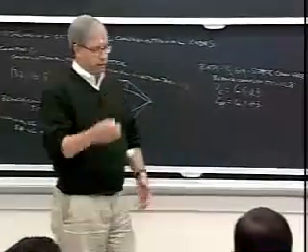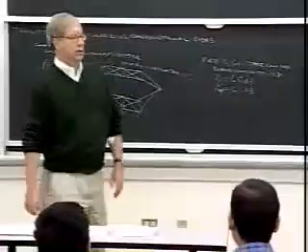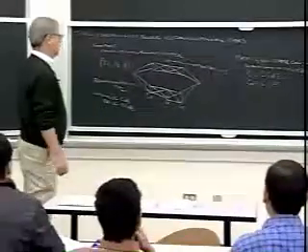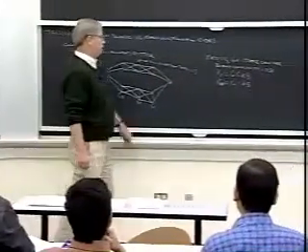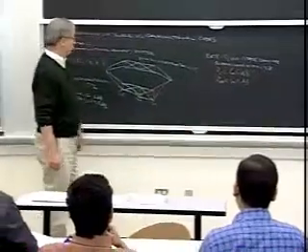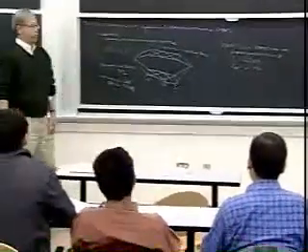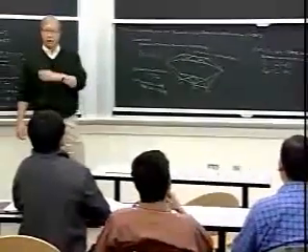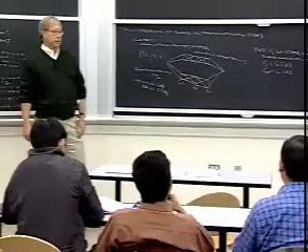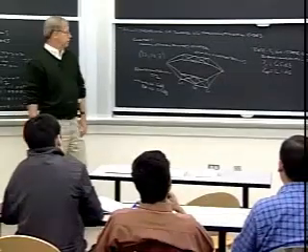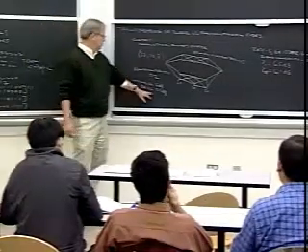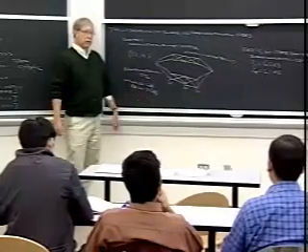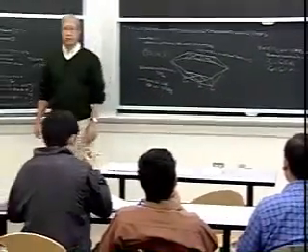If you try to plot a graph of this, you'll see that the effective coding gains of convolutional codes with the same state complexity are at least 1 dB better, as a general trend, than those of block codes. And if you do it in terms of branch complexity, it's an even better comparison.